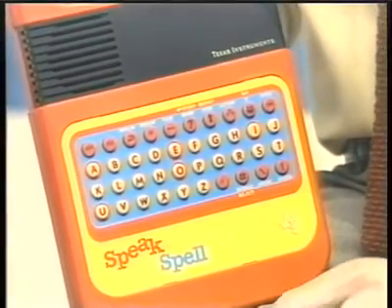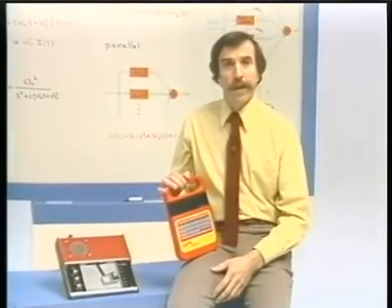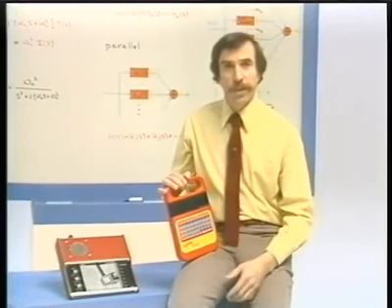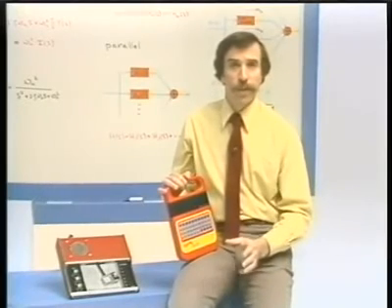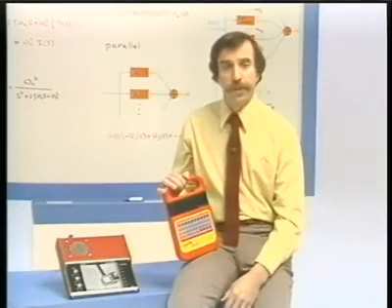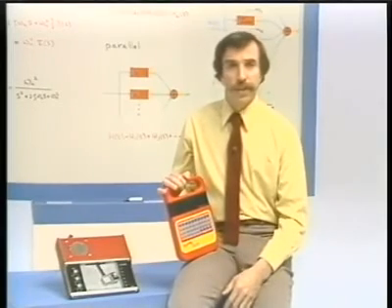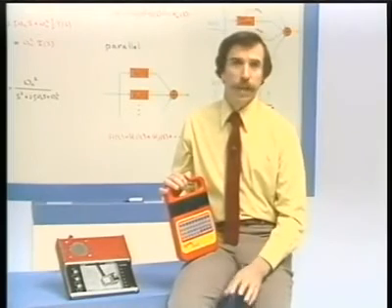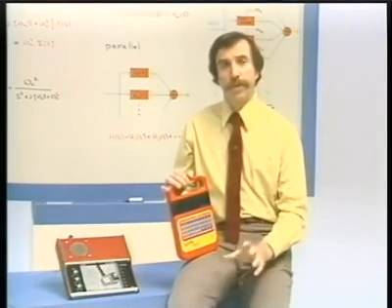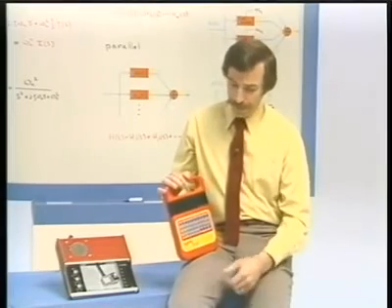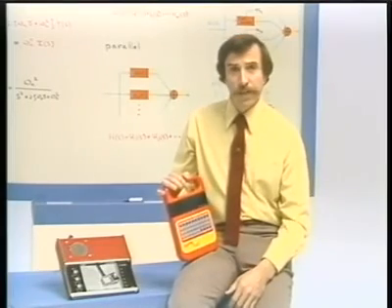And what's very interesting and rather dramatic about this device is the fact that it implements the speech synthesis in very much the same way as I've demonstrated with the analog synthesizer. In this case, it's 5 second-order filters in a configuration that's slightly different than a parallel configuration, but conceptually very closely related.